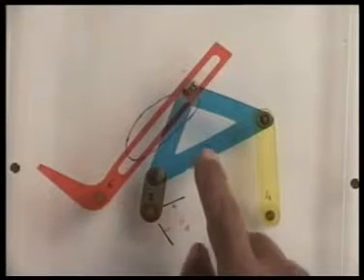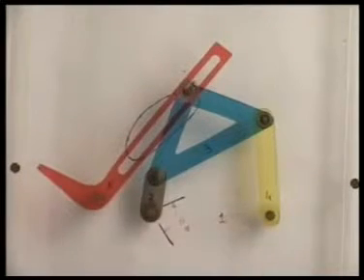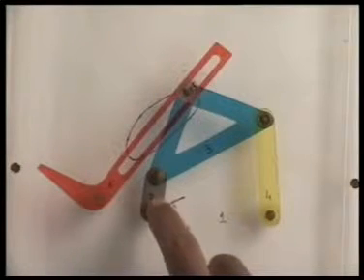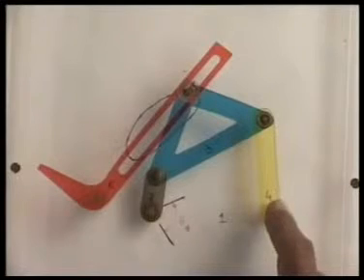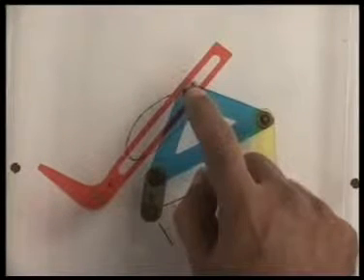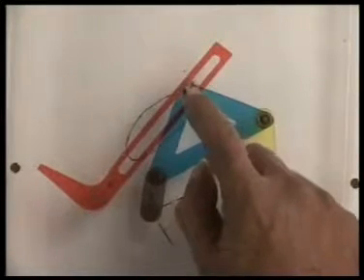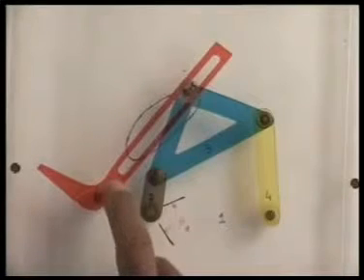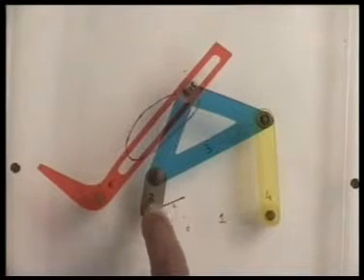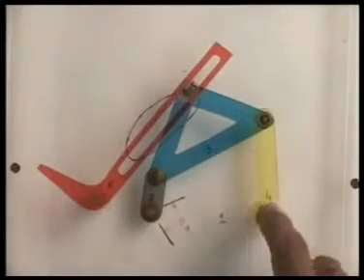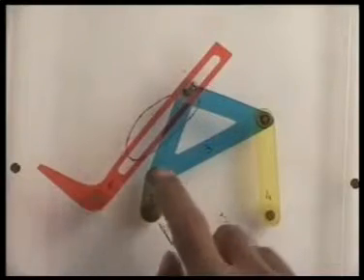Let us look at this model of this 6-link dwell mechanism. These links number 2, 3 and 4, as I said, constitute a 4R linkage, and this is the coupler point C. And there is a prismatic pair between this link 5 and the output link 6, which is hinged at this point, which we earlier called O6. This is O2, A, B, O4, C and O6.